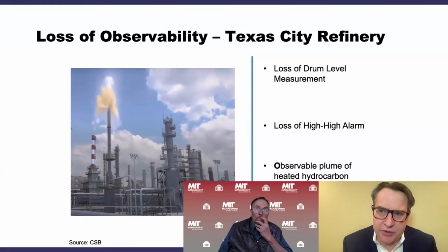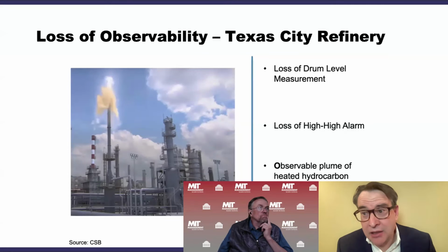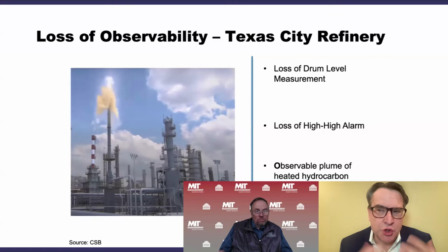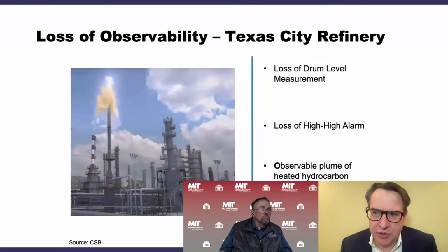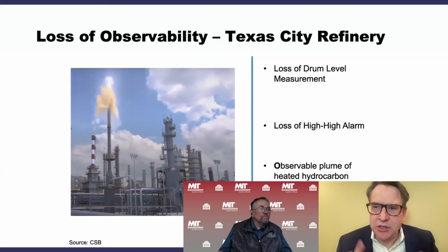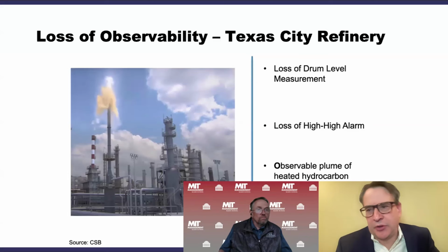You can basically call those digital twins at this point, but basically, 30 years ago, when you built a distillation column, you ran a mathematical model of it, or that's what I did. Today, you can run that design algorithm during operations. So if you're collecting certain vibration and thermocouple data, flow data, and you bring that into your real-time model, which let's call it a digital twin, since that's what's currently used, you can at least detect that something's gone wrong.